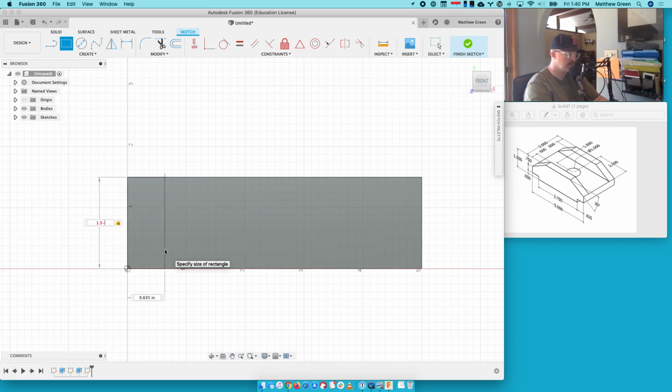So I'm just going to do a subtraction problem. 1.5 minus 0.75 minus 0.5 leaves me with that height, except shoot, I pressed enter and I still have this to deal with, and I don't know if that's the right length. So I'm going to grab the dimension tool and tap on this piece, and it says 0.635, that's not right. It should be 0.625. So I'm going to type 0.625 and watch what happens when I press return. It changes its size slightly, which is cool.